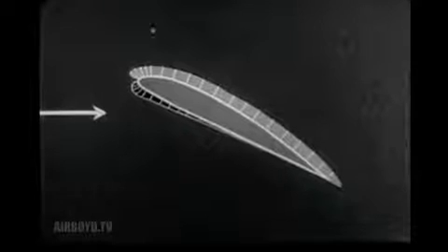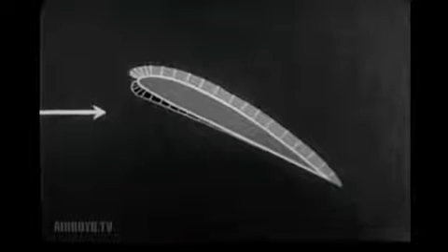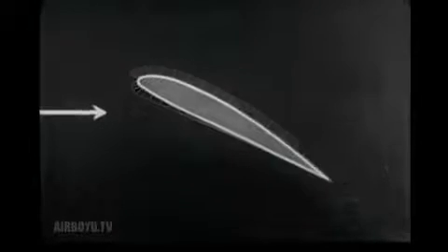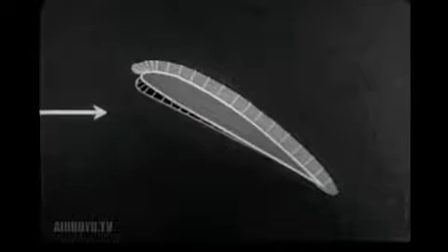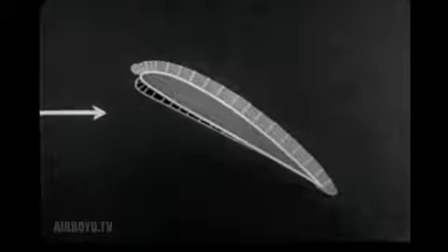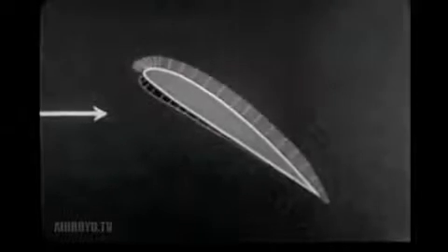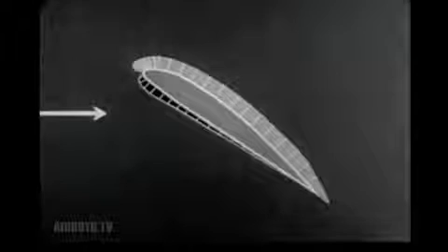At this angle of attack, the forward protuberance disappears completely, and an area of nearly equal negative pressure blankets the entire upper surface of the wing. Positive pressure areas still show no important change. Another increase in the angle of attack merely results in increased values, distribution remaining almost the same as before. At this final angle, pressures have reached still greater values without any appreciable change in distribution.